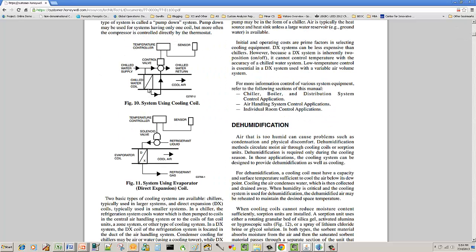Oh wow, doesn't this look similar? Yes, if you've mastered a hot water valve, you can understand a chilled water valve. The big difference is hot water valves typically control between 90 and 140. Electric heat coil may get up to 160, 180. Chilled water coils typically control to, if you've got a 42 degree supply, ideally you want a 55 degree discharge. When you're talking fan heat gain, you're looking at a 50 to 52 degree discharge off a chilled water coil.